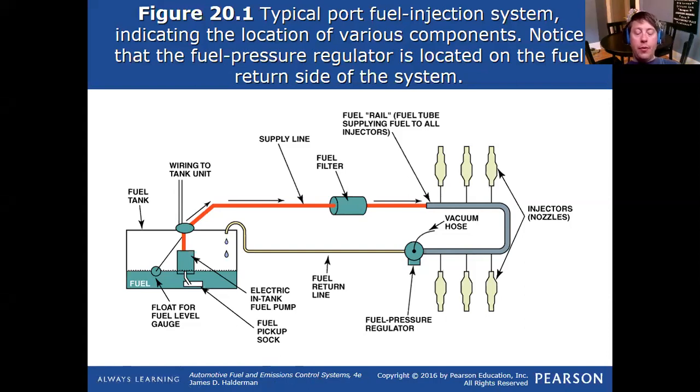So as you guys read through the chapter, fuel systems can come in a few different formats. They can lay them out a few different ways. In the past, we used to use this return style system that you see on the screen. This was very common. Manufacturers have gone more to the returnless systems, especially with the pulse width modulated fuel pumps. So as we are controlling the fuel pump via pulse width modulation, and we don't have a regulator in the system, as you see right here, we don't really need to have a return line.